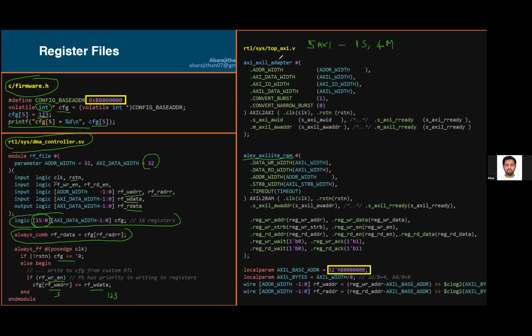The reason I'm doing this is that later on I'm putting all of these through an interconnect. I want to keep things as full AXIS because in Xilinx FPGAs, if you have full AXIS, you can directly connect it to the Zynq PS, the processing system. Otherwise, when you connect it, it creates its own module in the middle, and that differs from FPGA to FPGA and makes the script more complicated. So I want to have just one. So I'm having a full AXIS port, even for configuration.